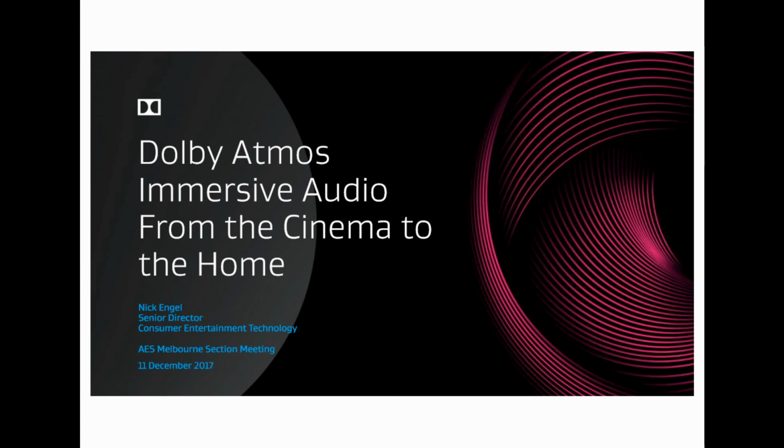Absolutely. Is there a special part for the bass, or the bass management? The LFE. Home's different to cinema. Cinema's way different, but absolutely. Managing low frequencies and bass is an important part. It's low frequency, so spatial is not important, but levels are, and you want to avoid clipping and all that sort of stuff. So the renderers typically take bass out and then take it down a different rendering path.